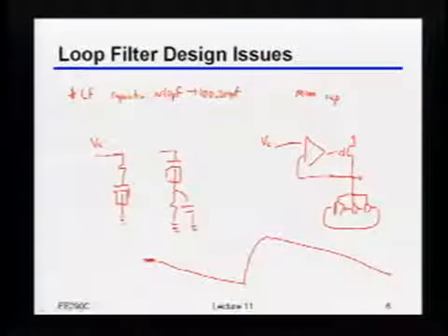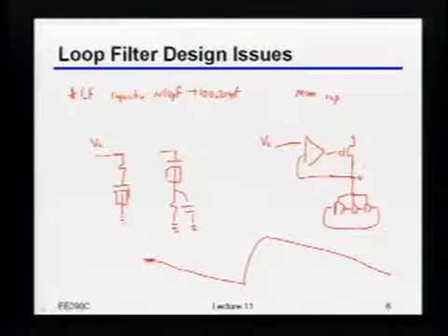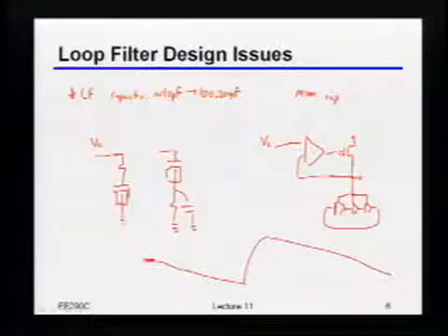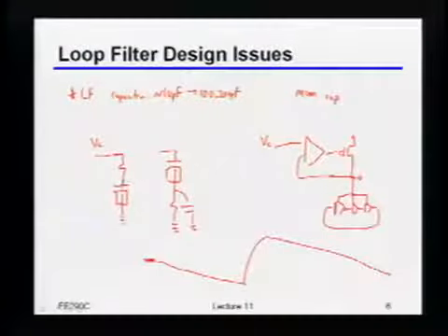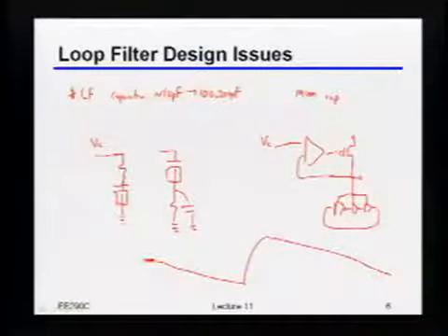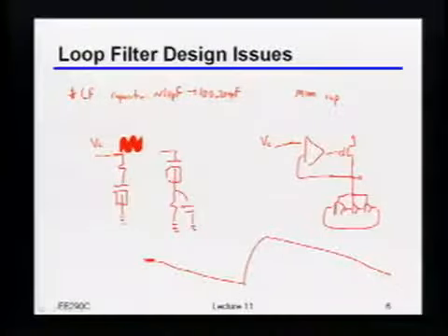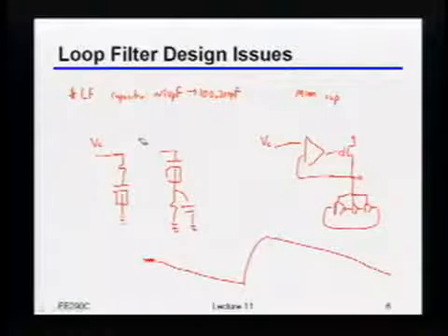I just have a question about MOSFET. So MOSFET is not that linear. It depends on your biasing voltage. Does it kind of modulate this control voltage a little bit based on where this voltage is? Yeah, so there's some debate about that, but especially if I have a loop that's like this, where I know that this is at a pretty reasonable bias point, the nonlinearity, first of all, is going to be fairly small. But second of all, remember, these glitches on the control voltage had better be pretty small themselves, because if they're not, that means you have a lot of jitter, right? So you're right, that does come into the picture, but I've never seen a PLL that was limited by that particular effect. But it's a good question.